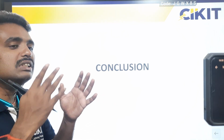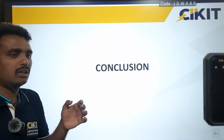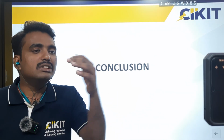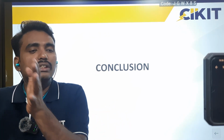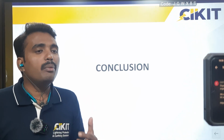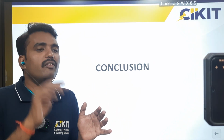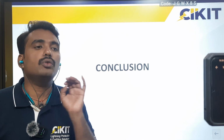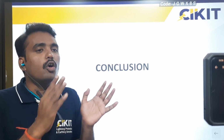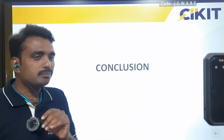So we cannot apply a generalized calculation for one building to all buildings. For each and every building, we have to calculate the risk components separately and go for a customized solution rather than a generalized one. It is not recommended to say that for a residential building we should always go for level 4. That we should not do. We have to perform the risk assessment calculation and, based on its output, select the suitable level of protection.